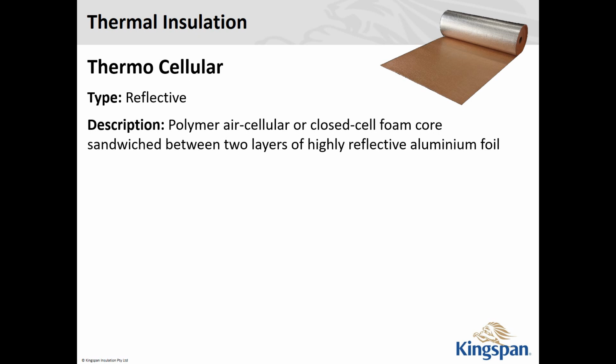Okay, so you've got the air cell or just sarking stuff underneath it? I just cut it to size, and I've just fitted it into the lids and the walls. Good stuff. And it's just reducing, I mean, if you're talking about site boxes, they obviously will be made of metal, I imagine, so they heat up in the sun and start to radiate a fair bit of heat. These sort of products are suitable for under your iron or tile roofs, in your walls and under the floors. We don't really recommend them being on top of the ceilings. So really under your iron, your walls or your floors.